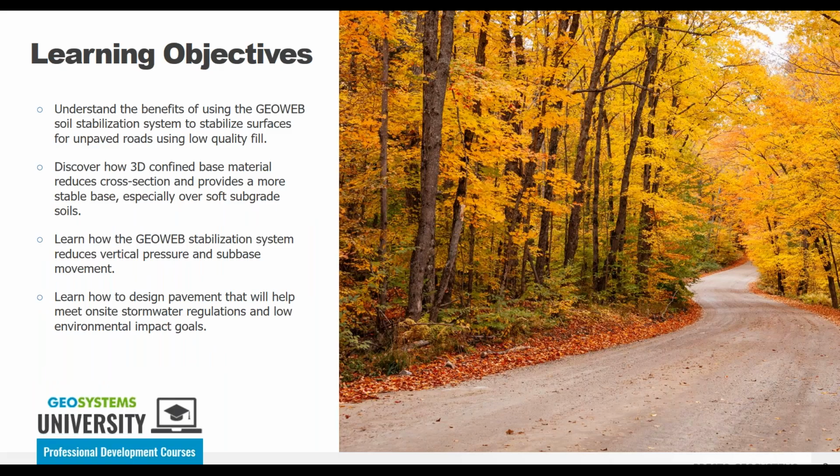So some of the things that I hope you get out of today's presentation: understand the benefits of using a soil stabilization system for both paved and unpaved roads, including using local low-quality fill and reducing your total cross-section depth, and building roads over soft subgrades. Then we're also going to cover how the system can reduce vertical pressures and subbase movement, and then how to utilize unpaved gravel surfaces for positive environmental impacts.